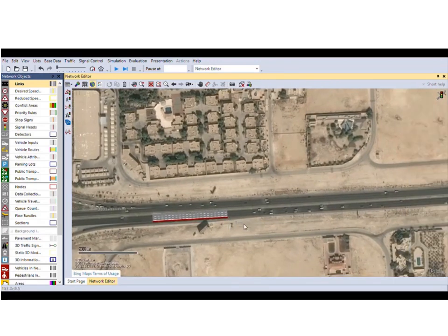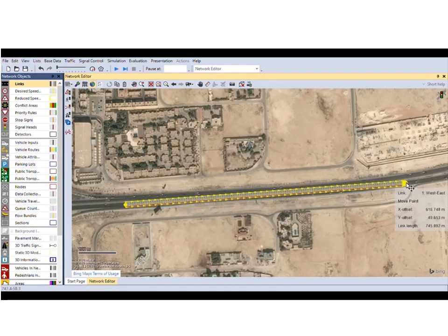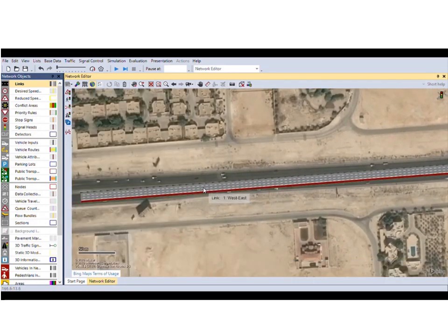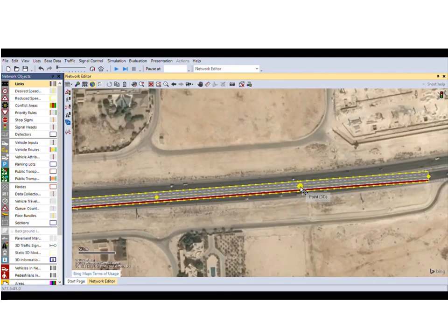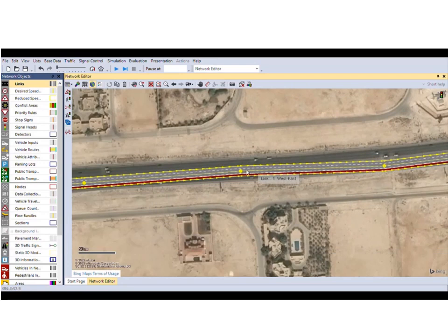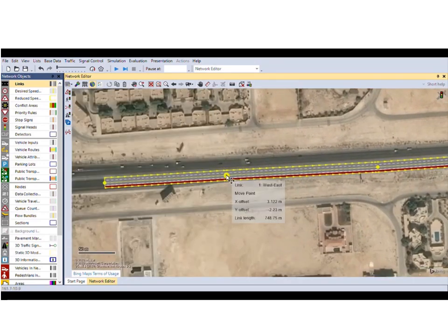And what we'll do now is we'll zoom out, you'll click on the road, and you'll drag one end all the way to the end of where you need your road to reach. Now, if you look, the alignment is not exactly correct. So what we do is you'll click on the road first, you'll right click on points on the road to add bending points. So now using these points, we can just shift the road and align it perfectly. Just drag and hold and realign your road.